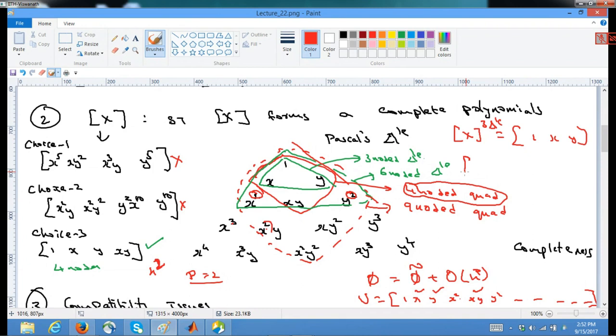This would be complete up to the second order, because all the linear terms have been taken care of here, and then this is the second degree things. So the third will be left out with the error function. And if I have to take 9-noded, then I'll take entries of 1, x, y, x square, xy, y square, not x cube, but x square y, xy square and x square y square if it is a 9-noded element. For 4-noded element, I'll take 1, x, y and x into y. So this is the choice of things that will give you the completeness.